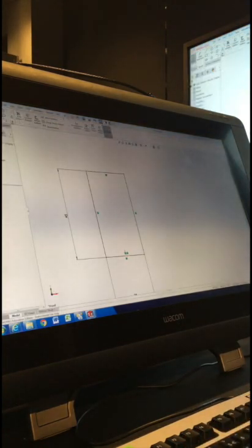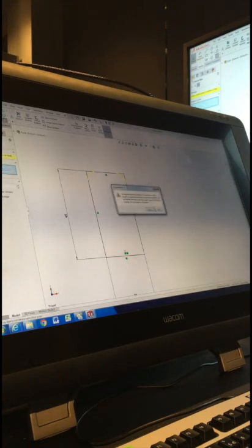So on my sketch toolbar, you see there's this sketch fillet option. You can select that and change the dimension to 5. And how these sketch fillets work, there's numerous ways. First way is you can select 2 lines and you can see the yellow preview between those 2 lines. Second, you can select a corner point and you can see the preview on that point. Or third, you can draw a box, and anything in that box it'll include. Okay, so it shows you a preview here.